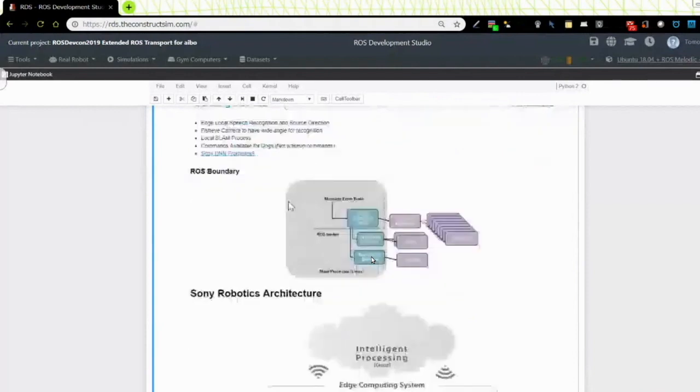We have some system perspective. We have some boundary for ROS. The body controller is ROS, so it's going to control the motion processor. But others, like the eye control or sound mixer, are not exactly ROS nodes, because we have to make a real-time quick reaction for eye and sound. So those are not ROS nodes.